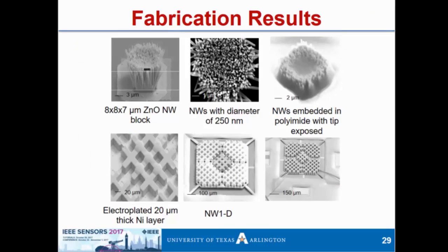So when they're built, and again, the amount of back etching that you do, the same as what we've done with the tactile sensors, determines not only the modulus for flexibility, it also determines the sensitivity that you're going to get. And you can really play with that to change the modulus of elasticity and also change the response.